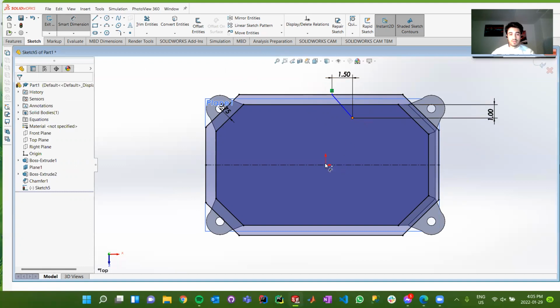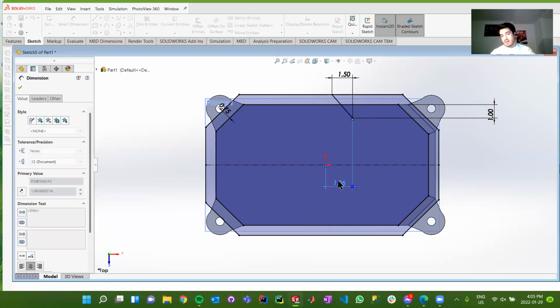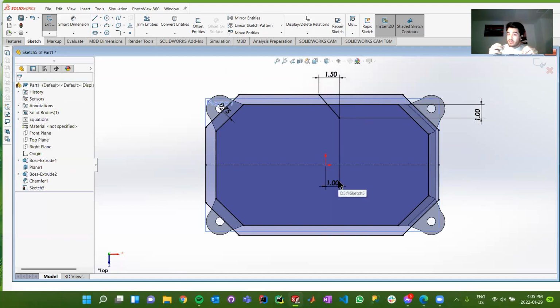So we'll say that this endpoint is actually an inch away from our coordinate system. And ultimately, if you ever want to constrain something by its position, you should do it either to its coordinate system or to existing geometry from before, ideally to its coordinate system though, because if you change your existing geometry, your actual component may be subject to change if you establish constraints to that existing geometry. Again, this may sound a little strange at first, but once you CAD more and more, you'll see what I'm saying.